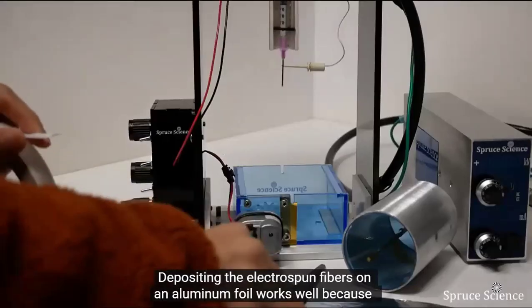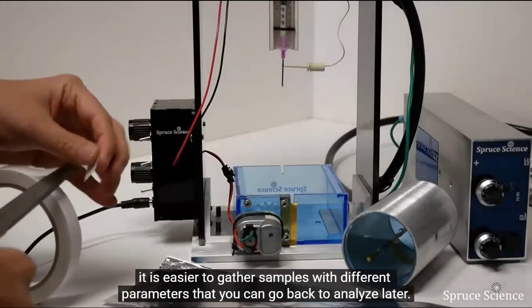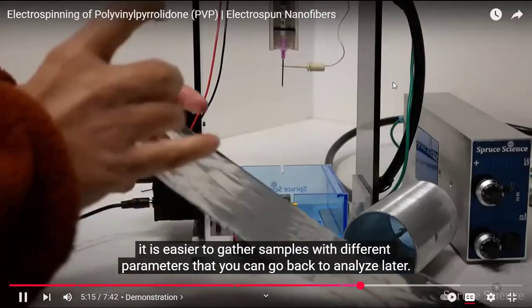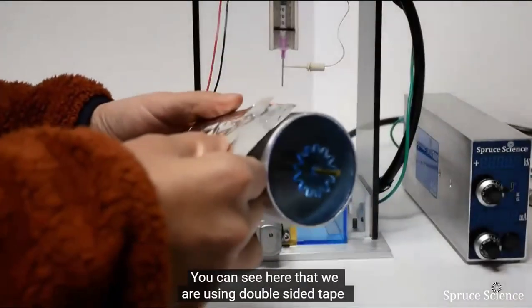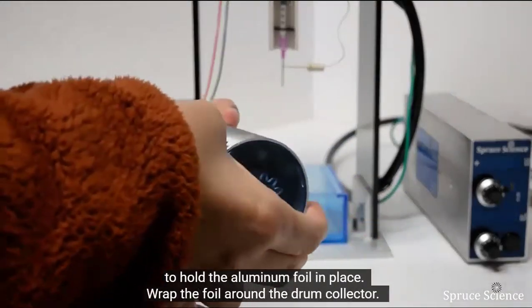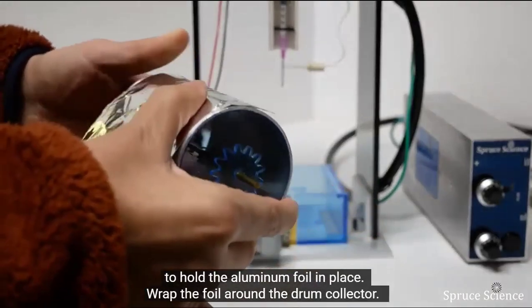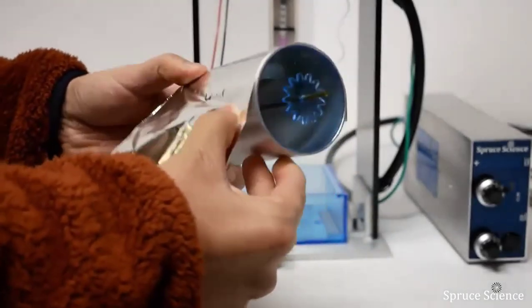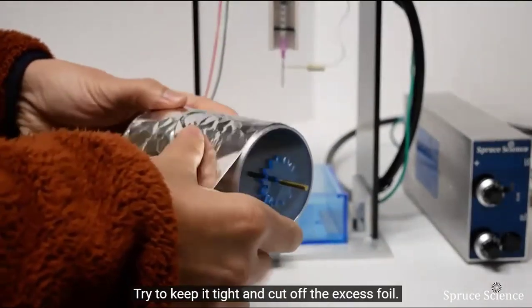Depositing the electrospun fibers on an aluminum foil works well because it is easier to gather samples with different parameters that you can go back to analyze later. You can see here that we're using double-sided tape to hold the aluminum foil in place. Wrap the foil around the drum collector. Try to keep it tight and cut off the excess foil.